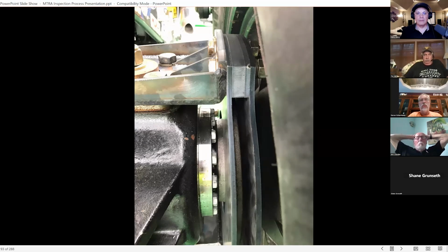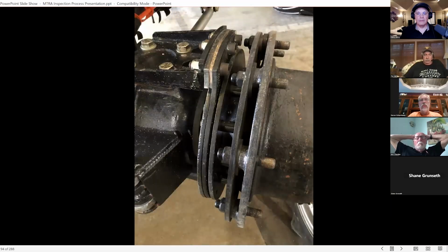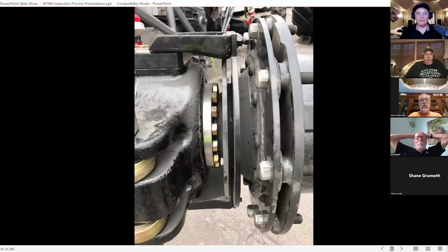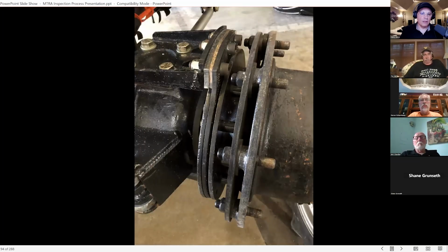Unfortunately, there are still wheels that fail or something that breaks, and it's either inboard or outboard of the restraint system. But with a broken spindle, or something along those lines, the restraint will grab it and do its job. And we've had situations where trucks were able to safely drive off the floor or back to the pits, even with a broken spindle, with this kind of system. So it works very well. You'll want to pay attention.